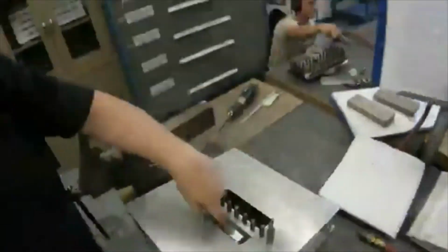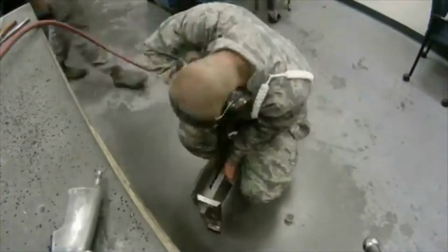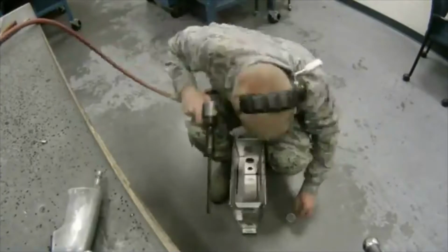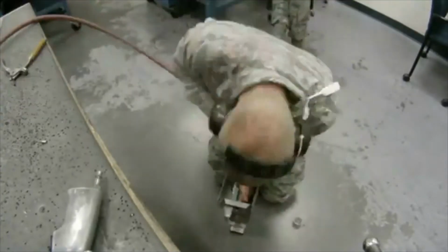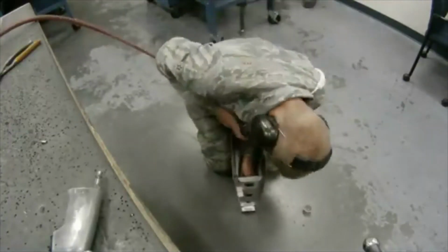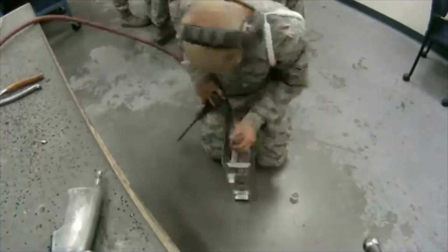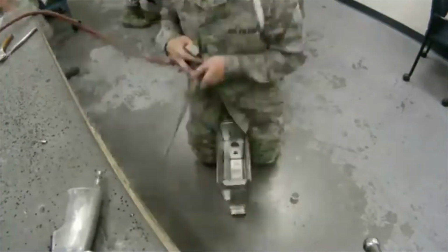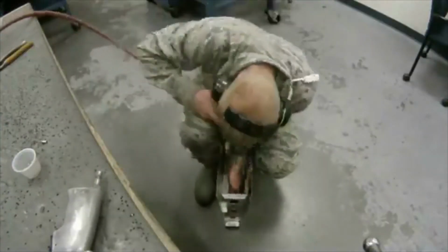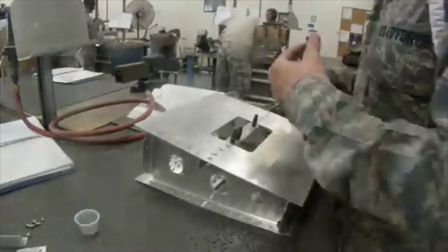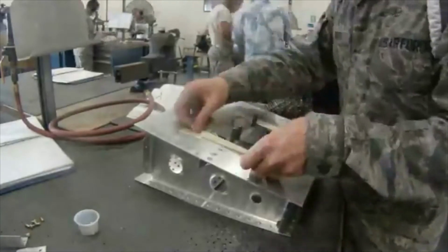Also inspect the surrounding members for evidence of corrosion and load damage so that the required extent of the clean-out of the old damage can be estimated accurately. After completing the clean-out, first make the layout of the patch on paper, then transfer it to the sheet stock selected. Then cut and chamfer the patch, form it so that it matches the contour of that particular area, and apply it.